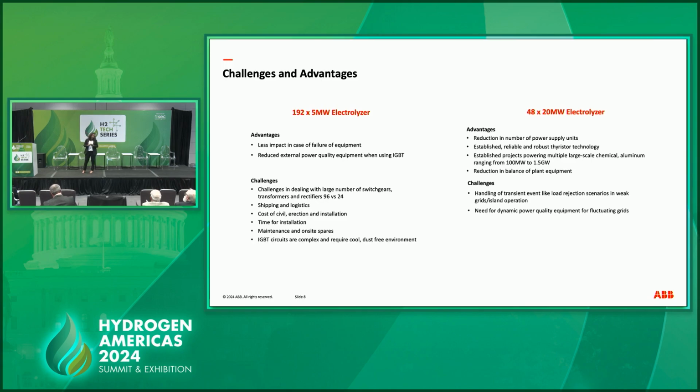And then after that, it's the after sales services, you have the maintenance of the on-site spares. And another disadvantage I would say is that the IGBT circuits tend to be more complex, they tend to be sensitive to temperature, and they require a dust-free environment.